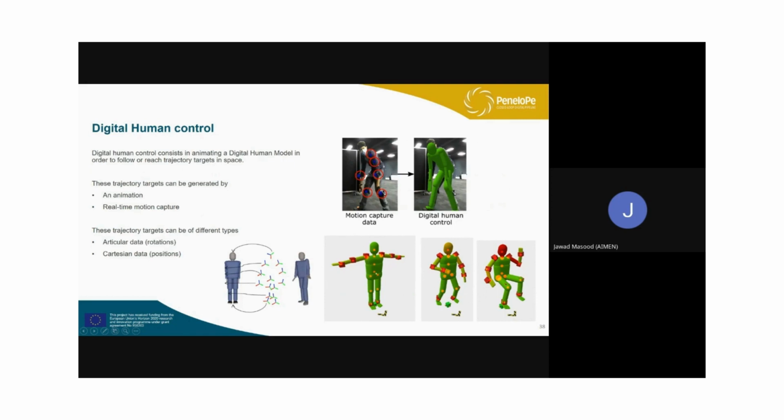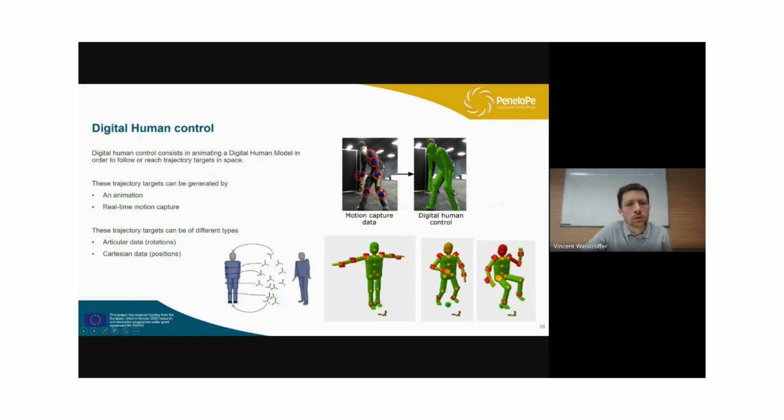So we have a specific damping and stiffness for internal joints of the human mannequin we show here. This can be changed, but here we use some template parameters that come together with our digital human model. So it's a template with specific damping parameters. You cannot really change them, but it could be possible if needed.